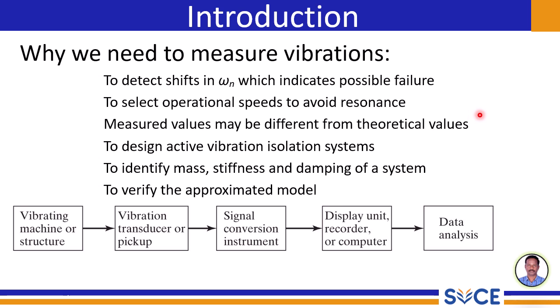Let's address a fundamental question. Why is it so important for us to measure vibration? Measuring vibration allows us to detect shifts in the natural frequencies, denoted as omega n, which can be a critical indicator for potential failures in machineries or structures.